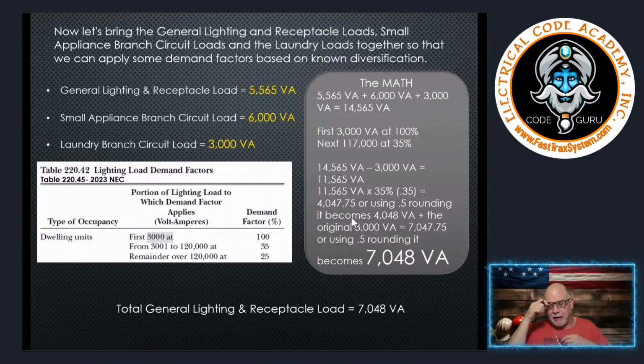Now, here's the first thing I'm going to remind you in this process. That is also neutral loads. We get to apply the same demands that we just did for the neutral as we're doing for the hot. So I recommend, when you're doing a calculation, to save you some time, although we're going to do the neutral quickly at the end here, just write it out in the column beside it, this open column. Keep track of your neutrals out here.